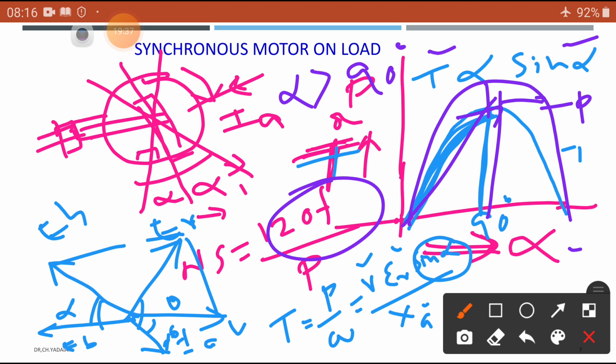When a synchronous motor is loaded, such as punch presses, shear compressors and pumps where there is a sudden load, its rotor falls back in phase by angle alpha. As the load is progressively increased, this load angle also increases so as to produce more torque for coping with the increased load, as we see.